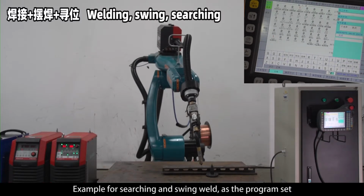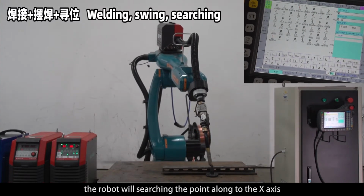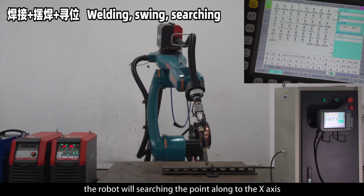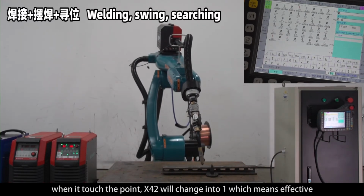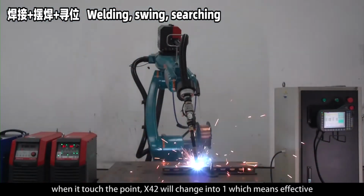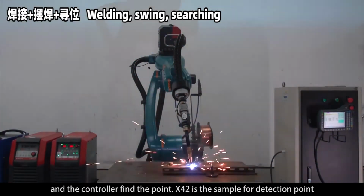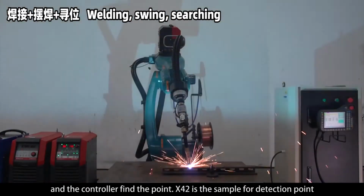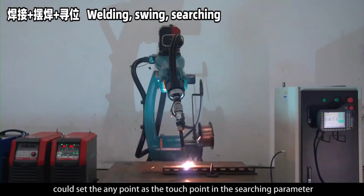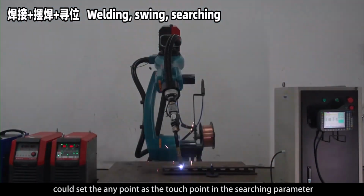Example for searching and swing weld. As the program is set, the robot will search for the point along the x-axis. When it touches the point, X42 will change into 1, which means effective, and the controller finds the point. X42 is the sample for detection point. You could set any point as the touch point in the searching parameter.